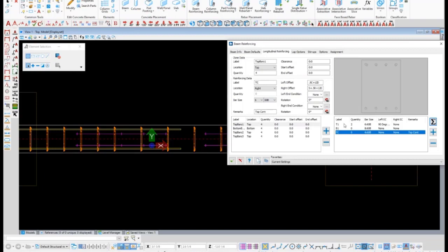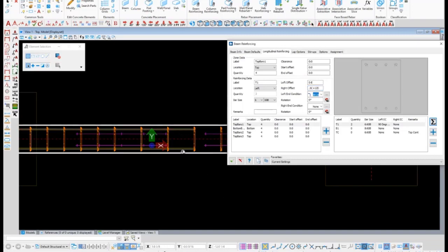And then whenever we go back and say, okay, now I'm at the center of my beam plus 12 diameter lap, it's going to take the bar diameter that I specified, a number 6, and say, okay, I need a 12 bar diameter lap, because when we look back at what the engineer was asking for, they wanted 24 diameters at the center. So if I have 2 bars that were intersecting, I need a total of 24. All I'm doing is taking that number, splitting it in 2, and calling it 12. So I have a 12 diameter lap, and that's going to add my distance required.